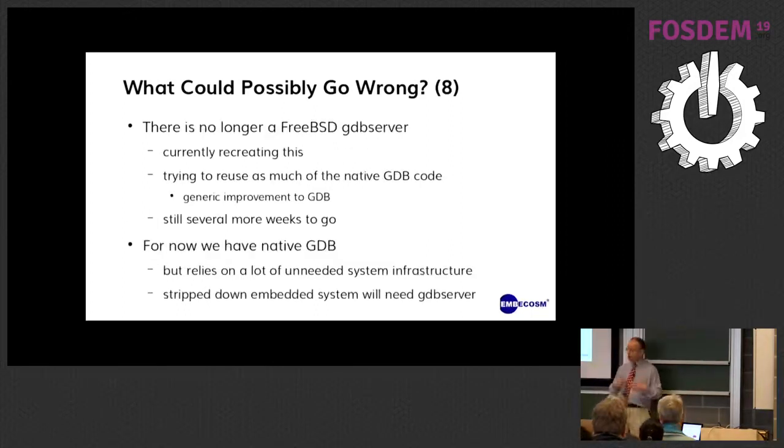Okay, so what else could go wrong? And the answer is debug. At the moment we have to debug by putting GDB on the target, and GDB works fine on FreeBSD. But that presumes, on a deeply embedded target, that we have a fairly fully featured FreeBSD, and secondly that we have the sort of console where I can sit there and browse. For a deeply embedded system, particularly in a secure application, which this is, you tend not to want more on there than you actually need.